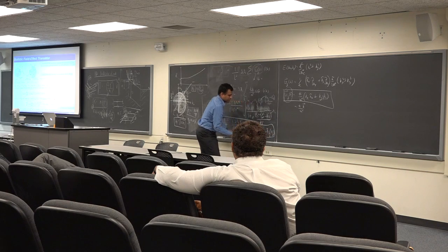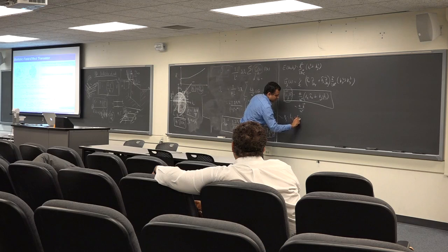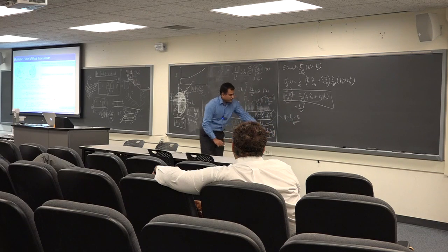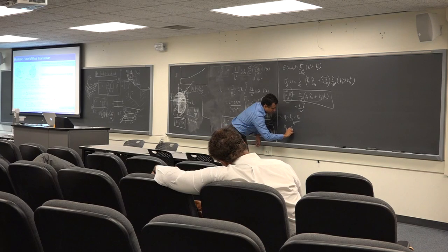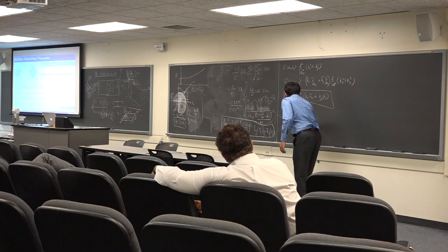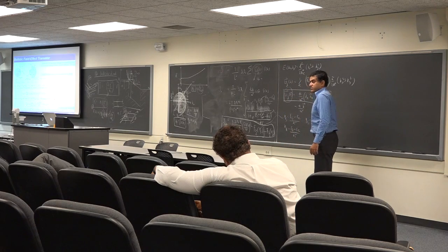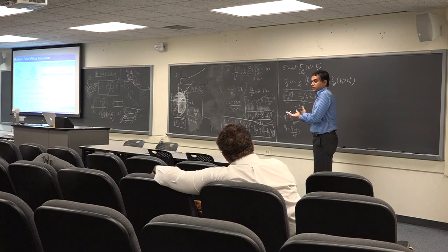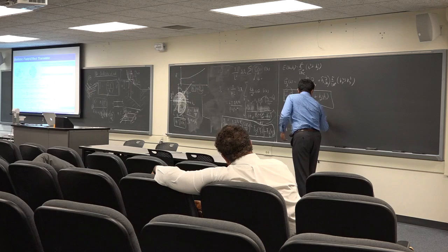And let me just make sure that it's clear. What is eta sub source? That is the Fermi level of the source minus conduction band edge over kT. What is eta of drain? It is the Fermi level of the drain minus the conduction band of the semiconductor over kT. What is eta source minus eta drain? That is the Fermi level of source minus Fermi level of drain, right? And that is just q times the applied voltage, right?